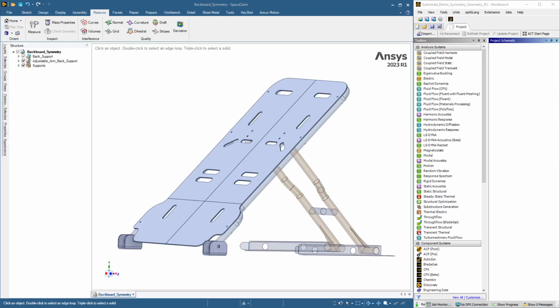Hello, this is a two-part series with Ansys Static Structural and SpaceClaim. In the first part, I'll be building a system model of mid-surfaces on some of this geometry and using fixed joints to check the design of the 6 bolts holding this flat plate to this pipe structure.